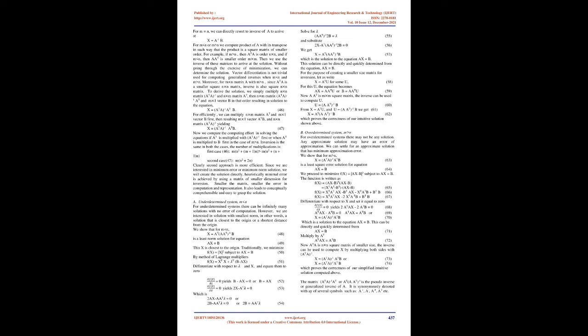V. Heuristic approach and justification for inverse Jacobian. The paper presents a heuristic method to solve inverse Jacobian for an arbitrary number of degrees of freedom, DOF, robot. The Jacobian inverse computation takes a long time, whereas first matrices must be multiplied, then the inverse of the product is computed, and then the inverse is multiplied with the transpose of the original to derive the generalized inverse. We will show how this is simpler and will apply this approach to both under and over determined systems of velocity equations. We also provide a better method for solving inverse Jacobian problems that avoid singularity in the solutions.